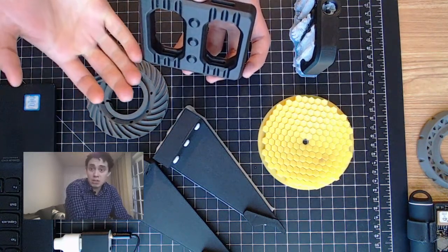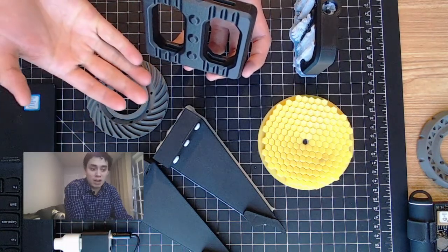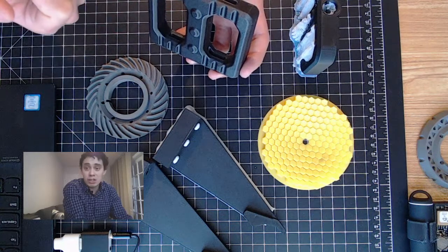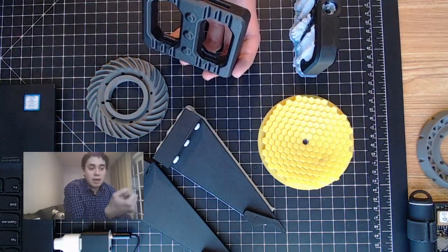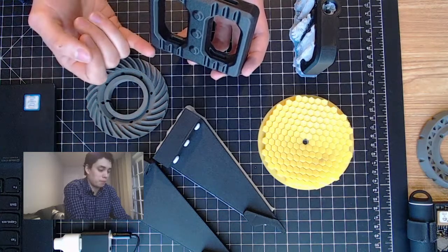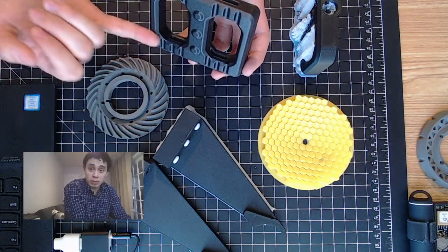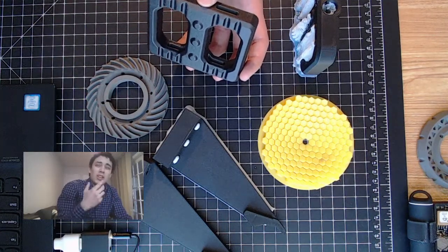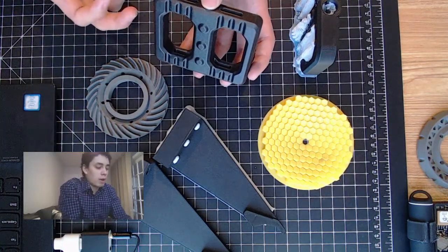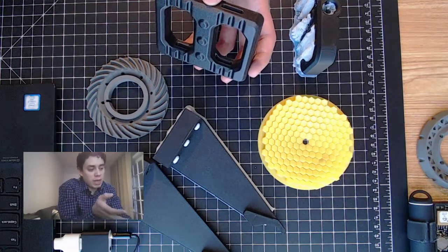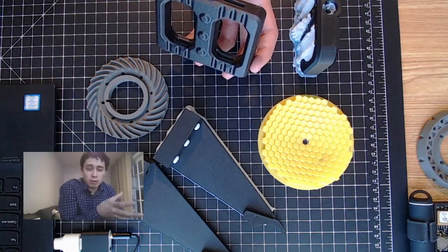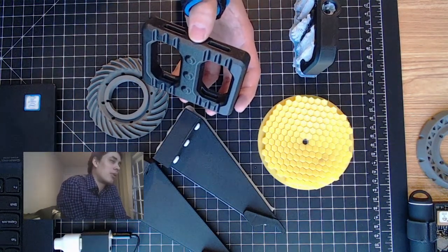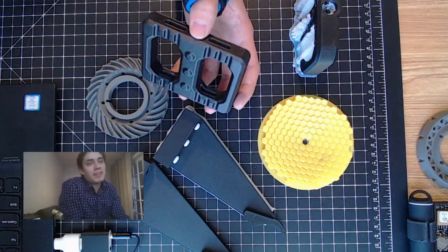By having more layers, technically you are adding resolution to that object, right? So if you imagine this object being sliced up into 1,000 layers versus 2,000 or 5,000, you can increase the number of layers and thus the resolution of the object. Now there's a limit to how thin a slice can be. Usually you'll hear manufacturers talk about somewhere between 100 microns and 200 microns, kind of like the standards. There are a few slicers out there that will allow you to slice for 50 microns or less.